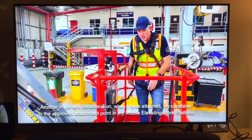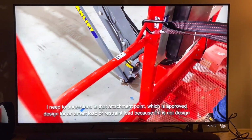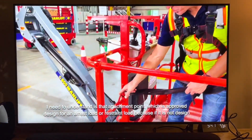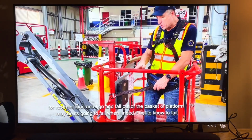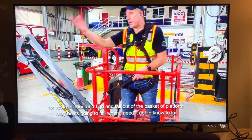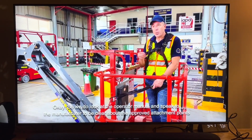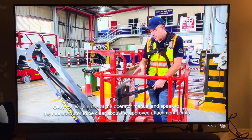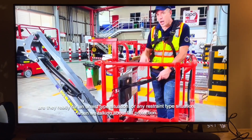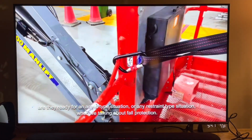Another important consideration: when I have attached my carabiner in my mobile elevating work platform, I need to understand whether that approved attachment point is designed for an arrest load or only a restraint load. Because if it's only designed for a restraint load and I fall out of the basket or platform, maybe it's going to fail when I need it not to fail. So we need to look at our operator manual and speak to the manufacturer to be clear about the approved attachment points. Are they rated for an arrest type situation or only a restraint type situation when we're talking about fall protection?